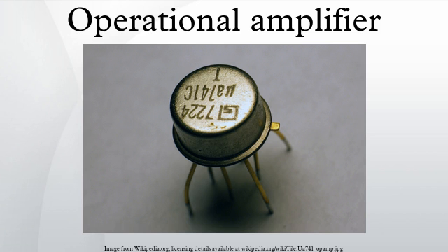Non-zero output impedance. Low output impedance is important for low impedance loads. For these loads, the voltage drop across the output impedance of the amplifier will be significant. Hence, the output impedance of the amplifier limits the maximum power that can be provided. In configurations with a voltage sensing negative feedback, the output impedance of the amplifier is effectively lowered. Thus, in linear applications, op-amps usually exhibit a very low output impedance indeed.